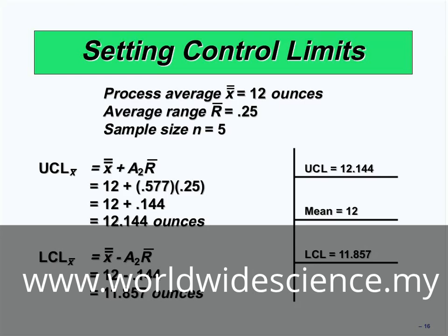Only in this method, because we don't know sigma, if you are working in a company where sigma is not given to you, you can use this method to determine the x bar chart, and through this identify whether the process is under control or not.